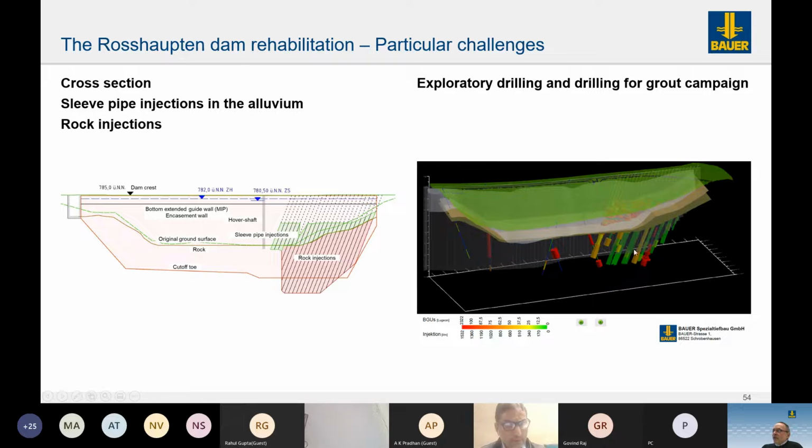You know exactly where your drilling rods are. You know exactly where the openings are for your grout. You know the volume of grouting, and this is data you will have readily available on an almost daily basis, not only on a daily basis, but on an hourly basis. When you install such an element, when you're grouting, you have this immediately on your screen.